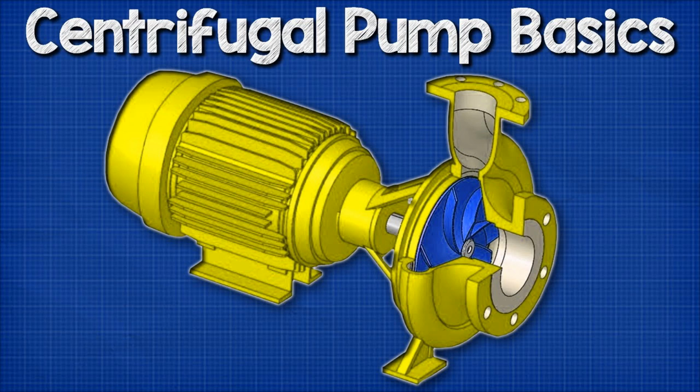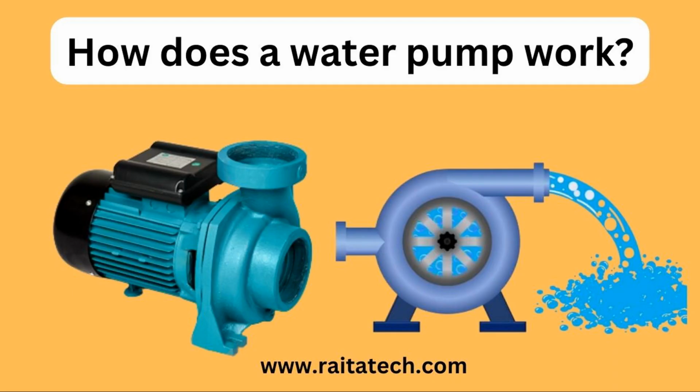Radial flow centrifugal pumps are a type of centrifugal pump where the fluid enters the impeller axially, along the axis of rotation, and is discharged radially, perpendicular to the axis of rotation. These pumps are one of the two main categories of centrifugal pumps, the other being axial flow centrifugal pumps. Here are the key features and characteristics of radial flow centrifugal pumps.